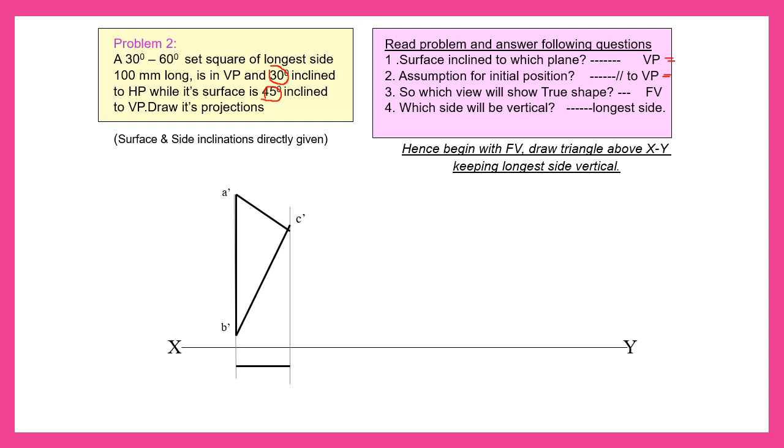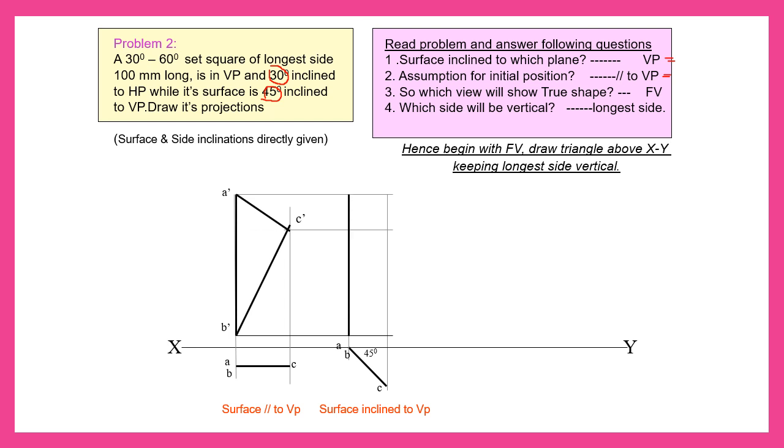What you are going to do is tilt this top view by 45 degree and project all these points, horizontally projecting the 3 corners. By projecting this you will get a shrinked triangle.